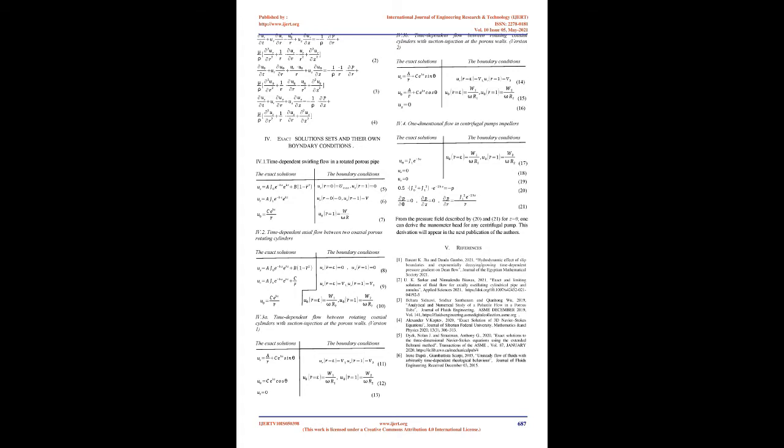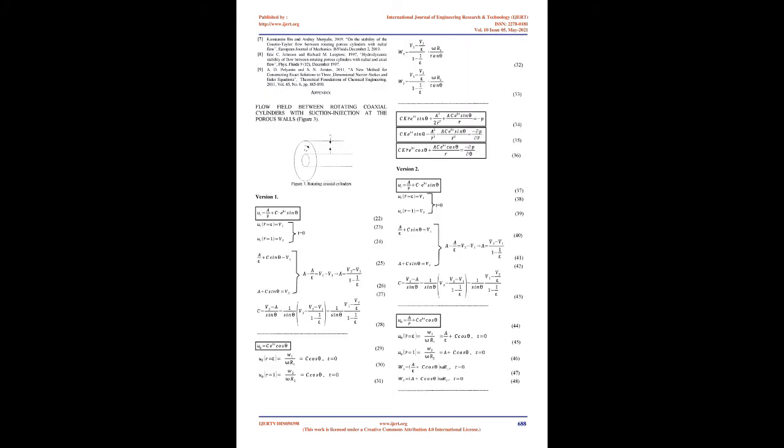Mathematical and physical modeling. For the first case study we assume the flow of a Newtonian fluid within a rotating porous cylindrical pipe, figure 1, and for the second case study the flow through an annulus formed between two rotating porous cylinders, figure 2. For the two cases, the basic equations are the mass conservation equation and the equations of motion, Navier-Stokes, in a cylindrical system of coordinates (r, θ, z) where the z-axis lies along the axis. Conditions in a rotating pipe. Figure 1. Flow within a rotating porous pipe. Axial flow conditions in two rotating porous cylinders. Figure 2. Rotating porous cylinders.